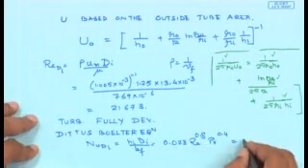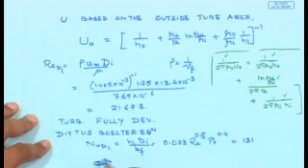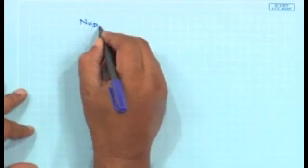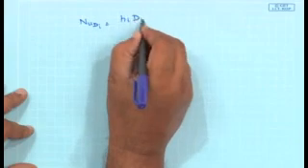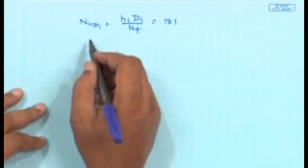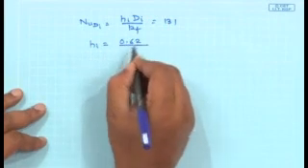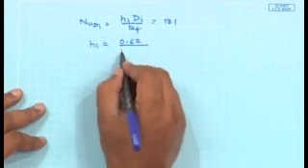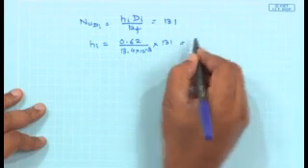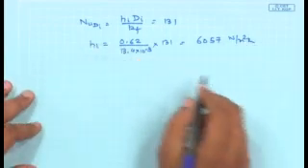And when you plug in all these values, this would be equal to 131, and from the Nusselt number based on the inside diameter, which is Hi di by Kf, since this is equal to 131, you should be able to calculate the value of Hi, which is 0.62 by di, which is 13.4 into 10 to the power minus 3, times 131, so it would be 6057 watt per meter square Kelvin. So that's the value of Hi.